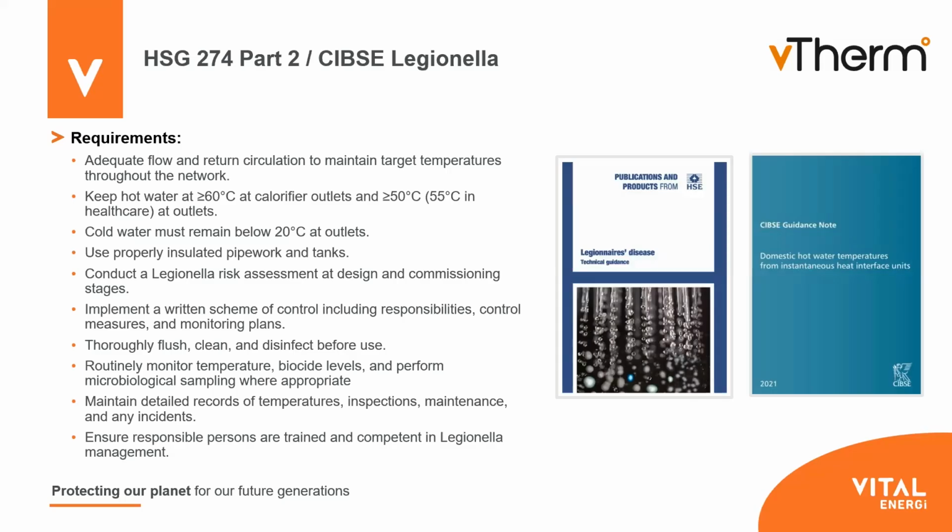We need to make sure that all our pipe work has been cleaned and everything is disinfected as required. And we've got to make sure that we can monitor temperatures, look at biocide levels and so forth, and do the appropriate sampling. And of course, along the way, you've got to make sure that you maintain detailed records of everything that is maintained and inspected as you're going along.